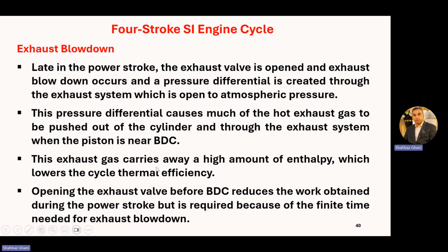Late in the power stroke, the exhaust valve is open and exhaust blowdown occurs, and a pressure differential is created through the exhaust system, which is open to the atmospheric pressure. Let me explain. This pressure differential causes much of the hot exhaust gases to push out of the cylinder and through the exhaust system when the piston is near BDC.